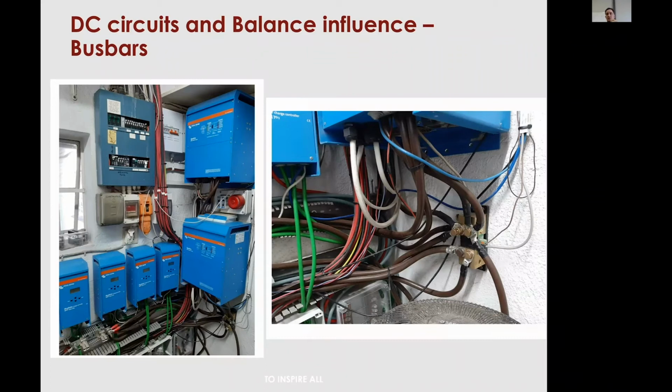He did actually start adding in DC cabling because he was getting too much DC ripple on the inverter. And by adding the cable, he managed to reduce the resistance and the impact of the connections, and therefore removed his DC ripple. But he didn't get enough of a balance to improve the lithium battery handling of the disparity in all the cables.